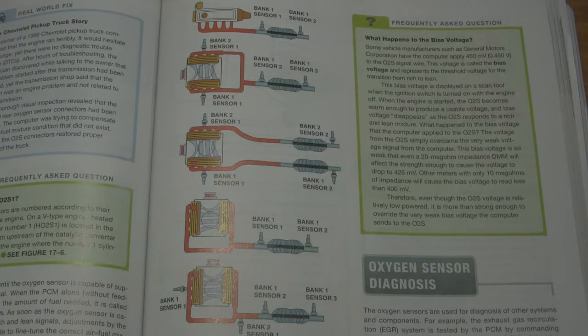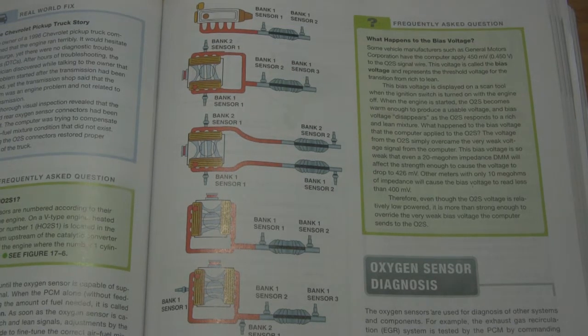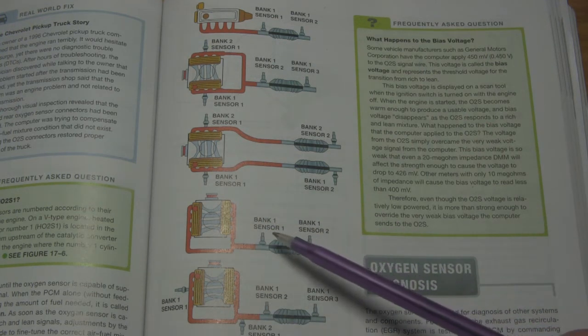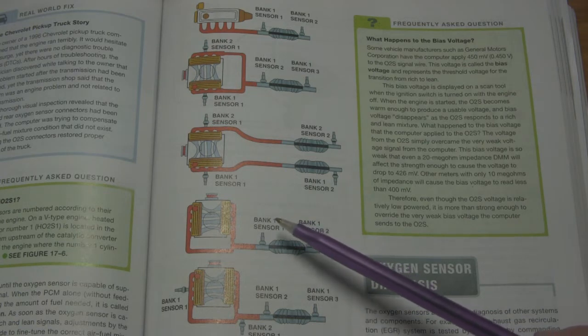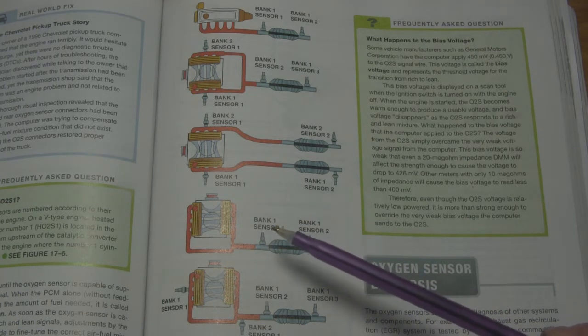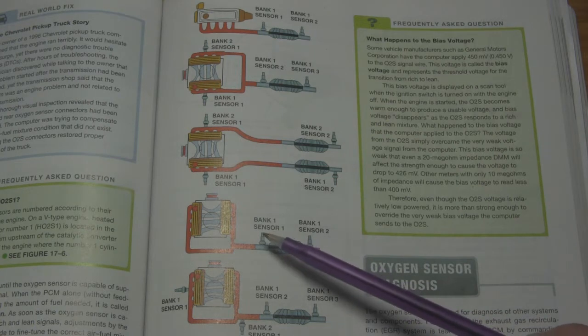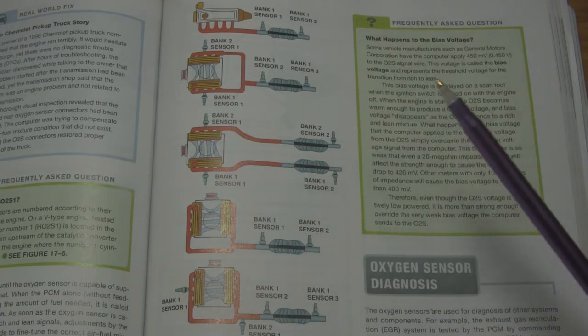Oxygen sensors will typically be referred to as bank 1 and bank 2. And so if we look at your conventional 4-cylinder engine, how many banks do you have? 1. You have 1 bank. On a V-type motor, you'll typically see 2 banks. On your older V-type motors, you'll still see just the whole engine operating on 1 bank. So this is one of the distinguishing factors between older OBD2 technology and newer OBD2 technology: the addition of a second oxygen sensor and a second bank.